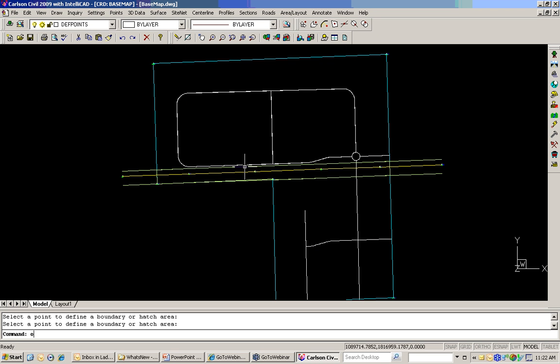I'm going to create and offset each of these, maybe a distance of, I don't know, let's say 300 feet to the inside. So we'll pick up that one right there and offset it inside, and we'll do this one and bring it inside as well. So I have areas of green space that I want to set up for playground equipment or fields or just open space for the houses and the lots that are going to be put in here in just a minute. So we've got a lot of our areas put in. I'm just going to get rid of my source entities. There we go. And I'll just redraw this.